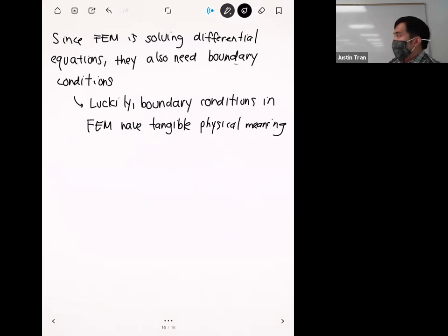We've applied a fixed support, where you can visually see what's happening: you're taking your geometry and fixing it at a certain location. The other type we've applied are loads, so forces and pressures, which are very easy to visualize. You're applying some kind of external load onto your geometry, and that manifests itself as a boundary condition.